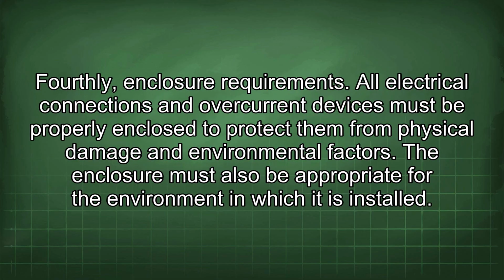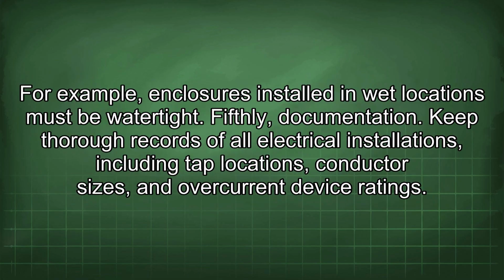Fourthly, enclosure requirements. All electrical connections and overcurrent devices must be properly enclosed to protect them from physical damage and environmental factors. The enclosure must also be appropriate for the environment in which it is installed. For example, enclosures installed in wet locations must be watertight.